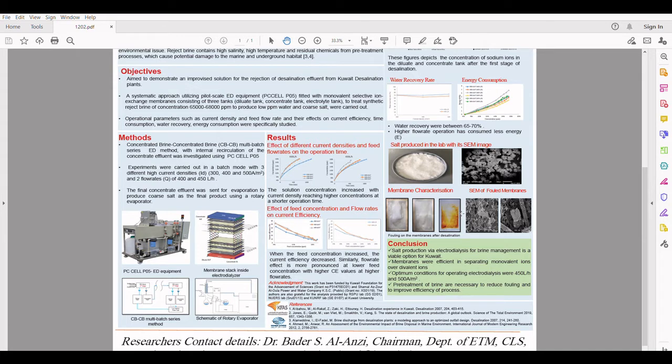We could find that most of the accumulated ions were divalent ions such as magnesium and calcium. This continuous accumulation of ions on the end cation exchange membrane led to cracks on the surface of the end membrane and thus resulted in the rise of electrolyte level in the electrolyte tank. In the next study, we will be using a modified electrodialyser unit.